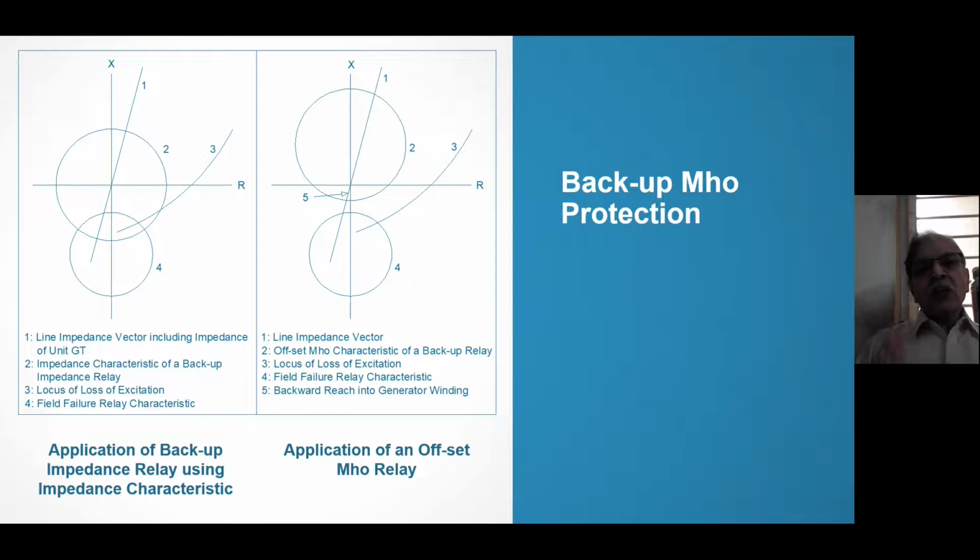You see, the fault has occurred on a transmission line. I have shown you the complete one-line diagram. That is, there will be a generator, then a generator transformer, then 52G, that is the generator breaker, then the infinite bus, and from there 7, 8, 9, 10, whatever is the requirement, lines will emanate.